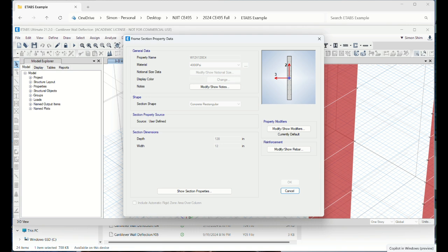Get it? Our form of 1, our loading is in plane, B is going this direction, right? Our associated moment of inertia should be about local axis 3. So the moment of inertia, when you calculate it, should be about this local axis 3. So you should calculate the width times length cubed divided by 12, right? In order to calculate the moment of inertia I.